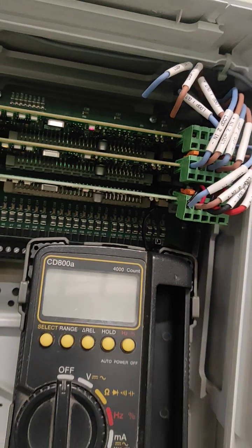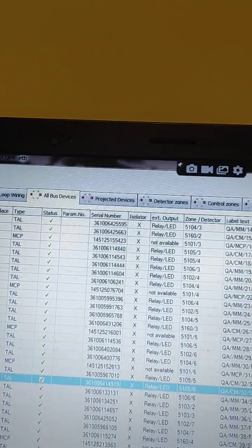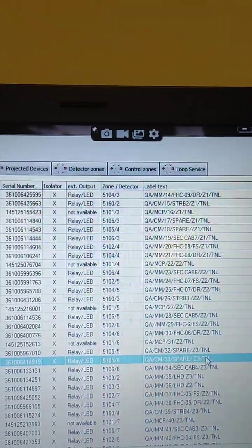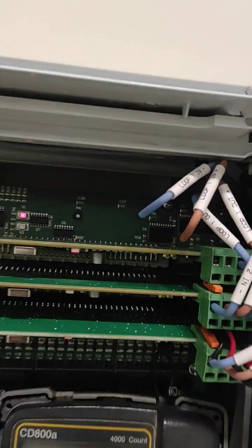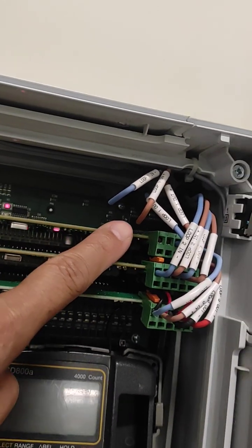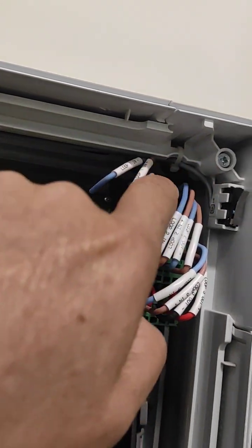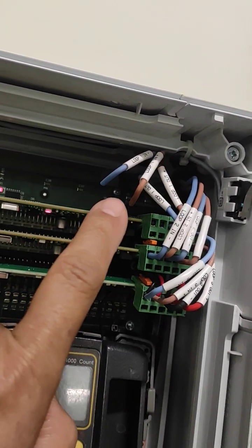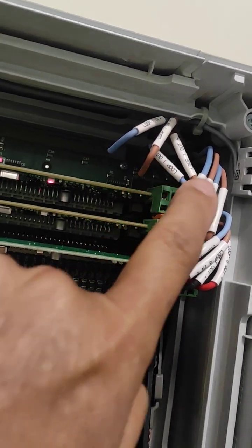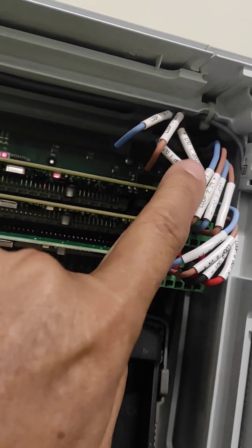This panel, and also the software, the Tools 8000, is not capable of using another loop cable. If both cables are connected to the loop card or SLC loop, there is a tendency to use the other cable. This is a very intelligent control panel. If you don't remove these two cables, the loop in or the loop out going to the first device, and the device has some problem, it can use the other cable if both are connected.